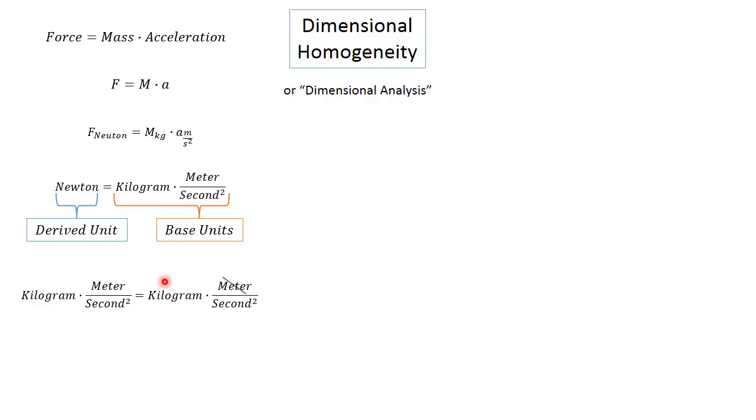Pretty simple, right? I'm actually going to take this a step further, do some simplification, and we get kilogram equals a kilogram. What this has done is prove that our equation up here is dimensionally homogeneous. It is a true logical statement. If this were, for instance, a meter instead of a kilogram, so we had kilogram equals meters, this would be a false logical statement.